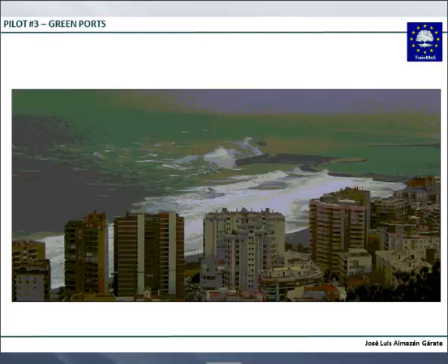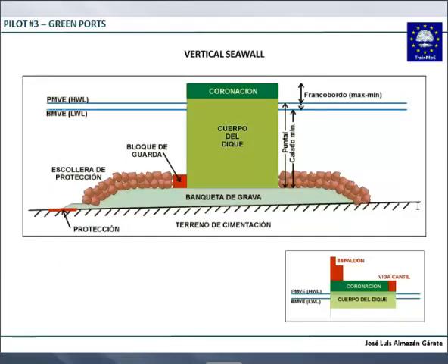You must be careful, because with dissipating structures, you dissipate energy. With reflection structures, you send energy to another place, far from where you have a protected area, but you still have the energy. You have doubled the energy content in that area. Very simple ideas, but very important, and a lot of misunderstanding in the port industry, even by specialists. It's astonishing how this thing works.